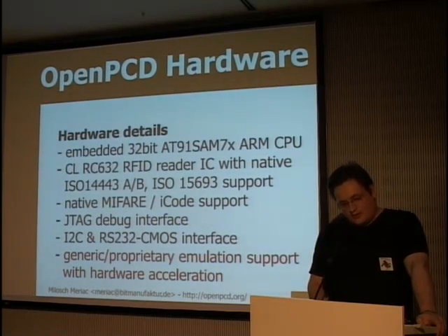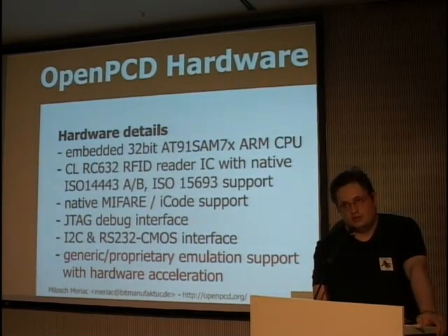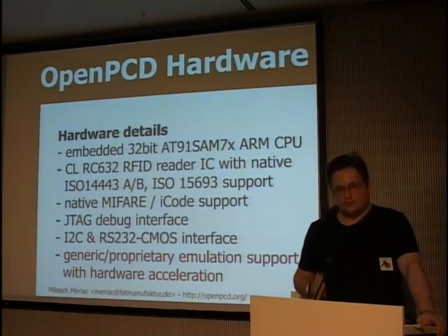The RFID reader IC natively supports ISO 14443A and B and 15693. But we wanted to provide also support for proprietary cards that are not directly supported by the reader IC itself. To make this possible, we provided an interface where you can basically bit bang arbitrary bit patterns on a DMA accelerated output.